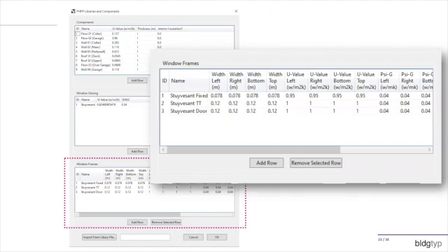And then window frames, of course, very similar to the way that we work with products in PHPP components or WUFI. You're going to enter all of your various frame widths and frame U values and solar G values, et cetera. And again, all of this can be imported from PHPP. So you do not have to write this out one number at a time. You can do it all in PHPP and have kind of a database, and then just import it all into your project.